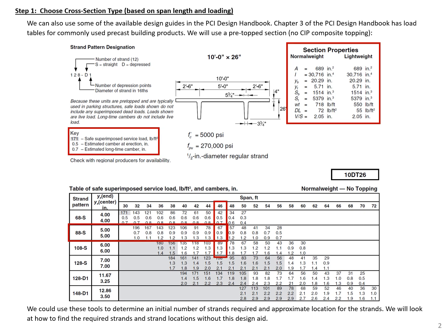If you're doing a precast building design, you're going to use the PCI design handbook. Chapter 3 has some information on preliminary design, and it has a number of different design tables for some of the standard precast concrete sections. We're going to use a pre-topped double T section with no cast in place composite topping.